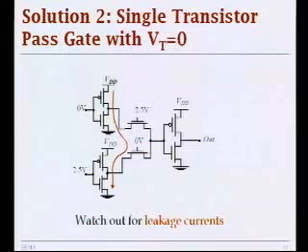But what happens? If you have zero threshold voltage, any variation in your input, for example, if I have this transistor here with a zero gate voltage input, then if I have a certain amount of noise or whatever, I can have a path going from here to here. Because this you want on and this you want off. But if VG is very close to the threshold voltage, then you would have leakage currents, and this would probably leak. And you don't want that.